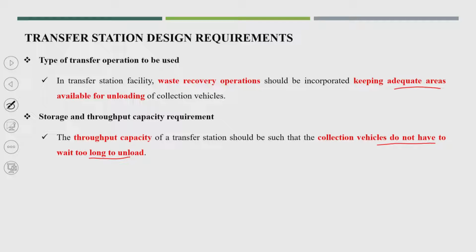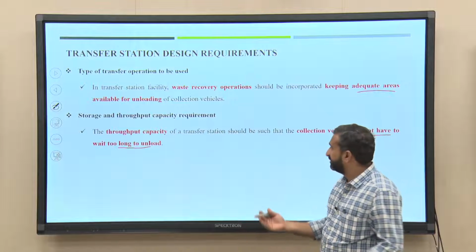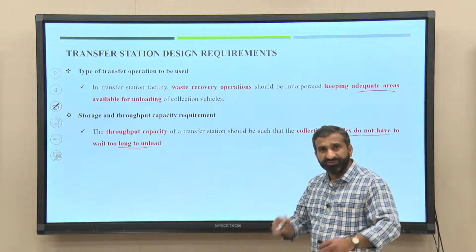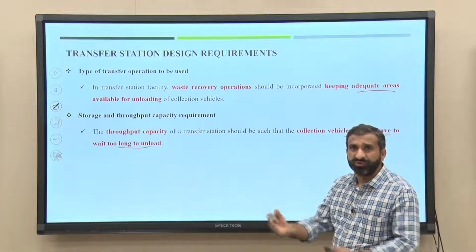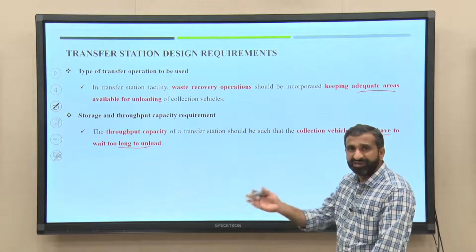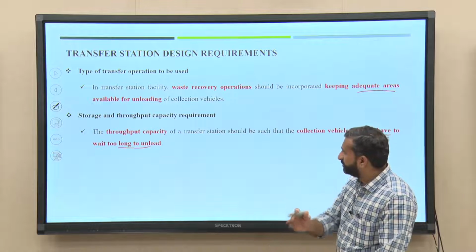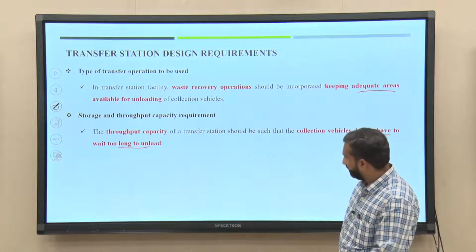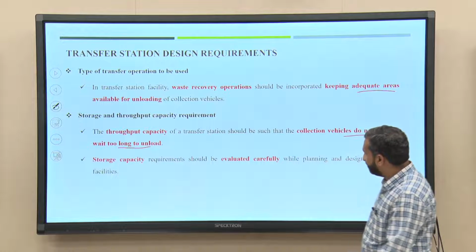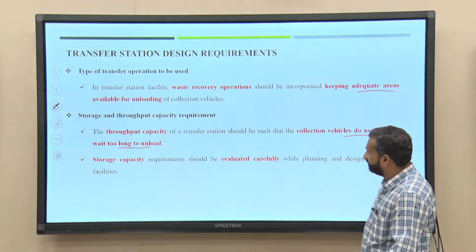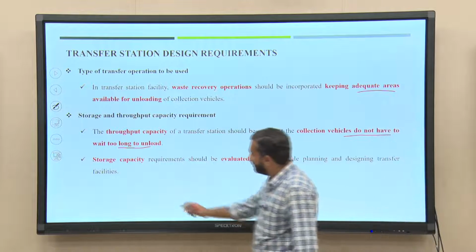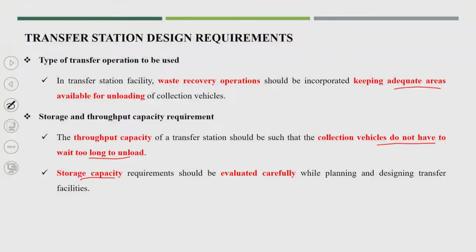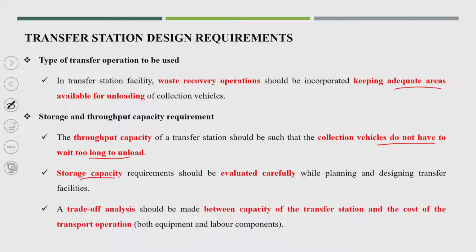Again, the proper area should be available, and even the storage capacity has to be looked upon to see that the entire waste could be unloaded into the transfer station. Storage capacity requirement should be evaluated carefully. The storage capacity I was talking about is so that vehicles do not wait for a longer period, and a trade-off analysis should be made between the capacity of the transfer station and the cost of the transport operation.